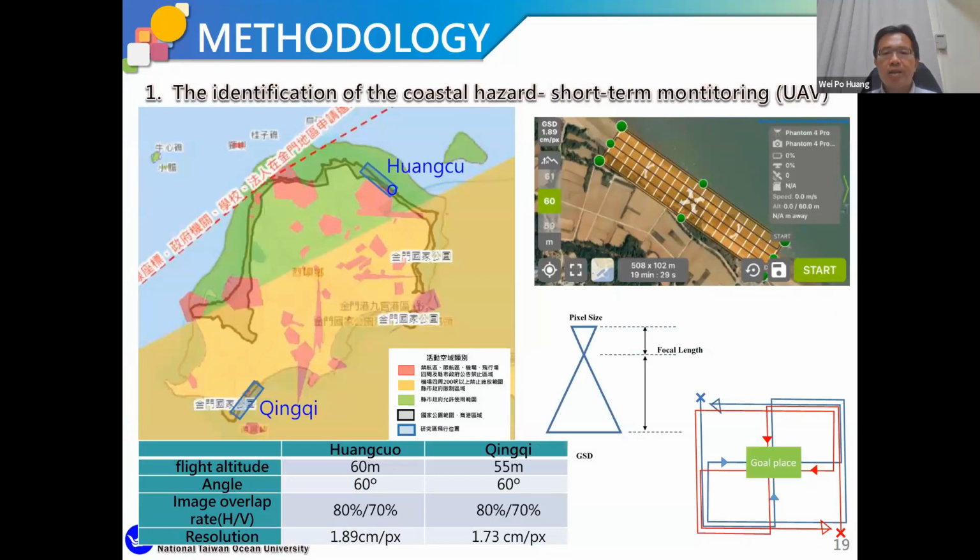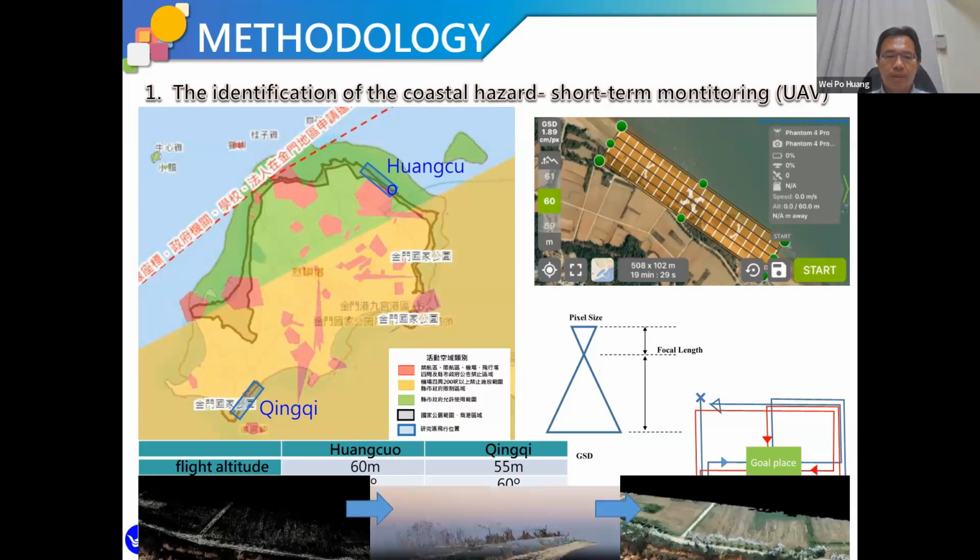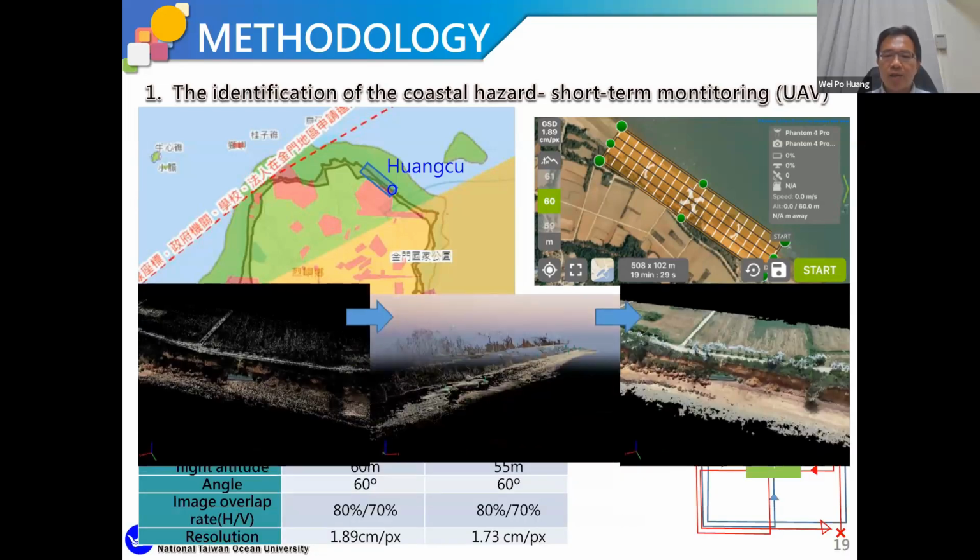In addition to satellite images, images obtained from unmanned aerial vehicles, UAV, were also utilized. UAVs for routine survey applications at the coast have come of age and are no longer the latest thing, more suited to the specialist researcher or amateur enthusiast. Off-the-shelf survey-grade UAV equipment, data processing, and analysis tools are now readily available to practicing coastal engineers, managers, and researchers. UAVs provide an efficient and cost-effective survey tool for topographic mapping and measurements in the coast zone. Structure from motion with multi-view stereo techniques produces fine resolution and spatially continuous 3-dimensional topographic data.